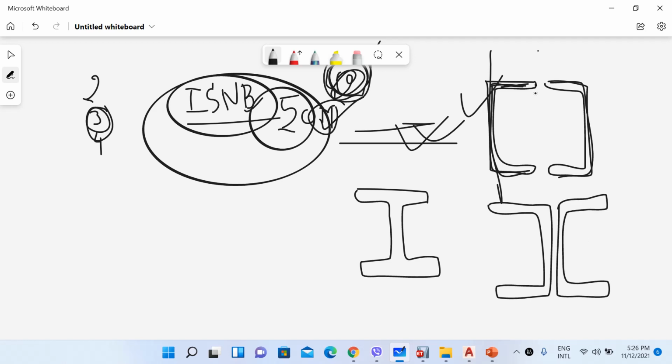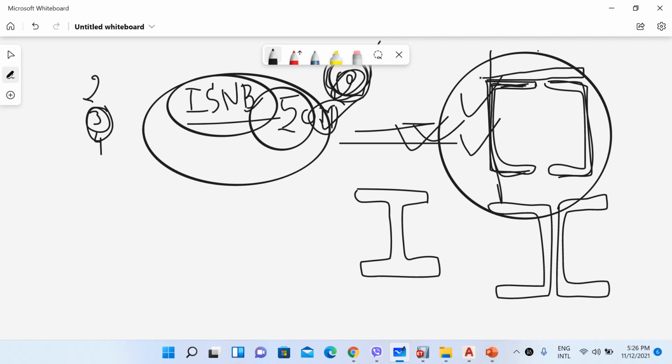So for now we will use section designer, since this cross section is not available in ETABS; we only have the single ISMC section. We will use section designer to create this section, and when we look at the design of columns in our design videos, then we will see how to create these columns and how to join them using batten plates.